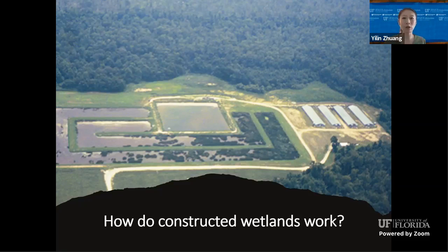Wastewater can either flow on top of the existing soil or through a porous medium, such as gravel. If it's above the soil, we call it surface. Under the surface, through the gravel medium, we call it subsurface. Flow is distributed evenly across the width of the wetland cell. A waterproof liner is used on the sides and the bottom of the cell to prevent leaks and assure adequate water for the wetland plants.